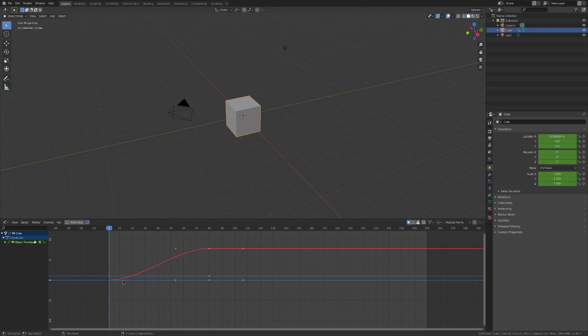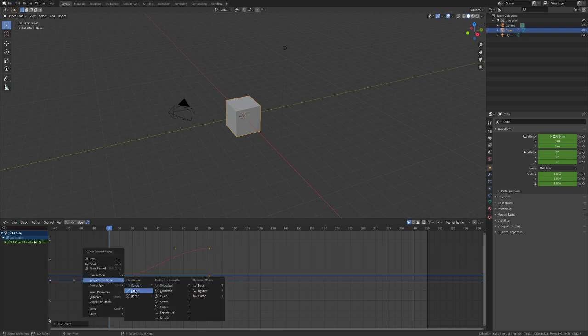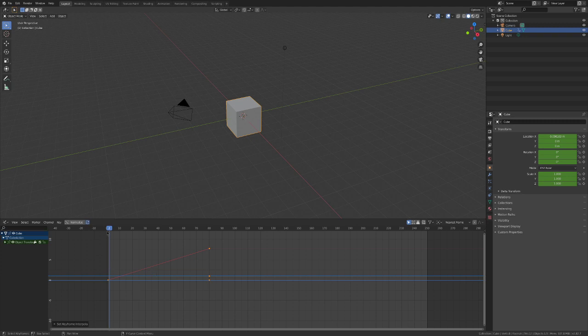Sometimes you need, especially when you do a loop, to answer to what we were saying before, if there is an acceleration and the slowing down, the loop won't be natural. You will see this slowing down continuously, and the loop is not going to be smooth. So what you want actually, it's having this as a straight line, and you can do it in different ways. You can do it from here, for example, or you can do it from where you were before. So you select the points you want to edit, and then you do linear, and now you will see the difference.